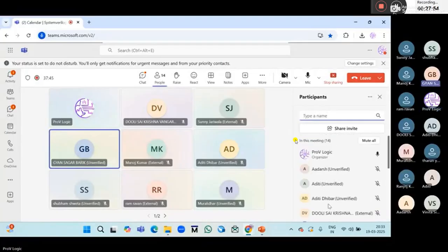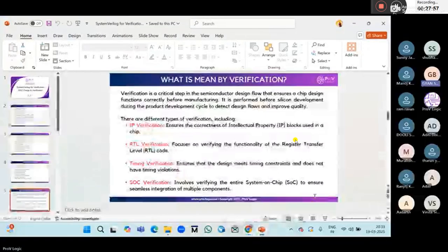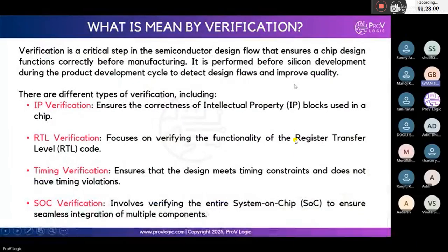Yeah, hi Prashanti. So actually, I have a doubt. As you mentioned, pre-silicon verification as well as post-silicon verification, right? Generally, post-silicon verification is also done by front end, or DFT, like you mentioned? Debug will be connected, different IP blocks are connected via debug, and after that some tool, right? So is this also done using SystemVerilog as well as UVM? Yes, we use SystemVerilog and UVM only, but post-silicon mostly means after the manufacturing process.